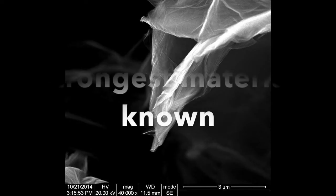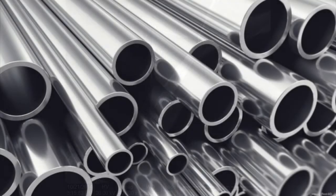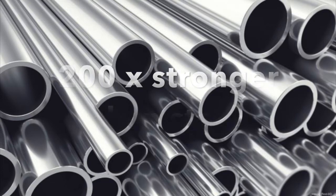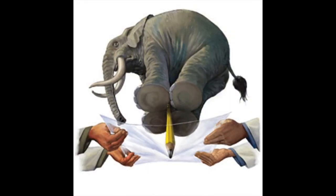Strongest material known. Graphene is the strongest material currently known to man. It has an intrinsic tensile strength of 130.5 GPa, which is more than 200 times that of structural steel, 400-550 MPa. To put it in simple terms, a 1 square meter graphene sheet would support a 4 kilogram cat but would weigh only as much as one of the cat's whiskers.